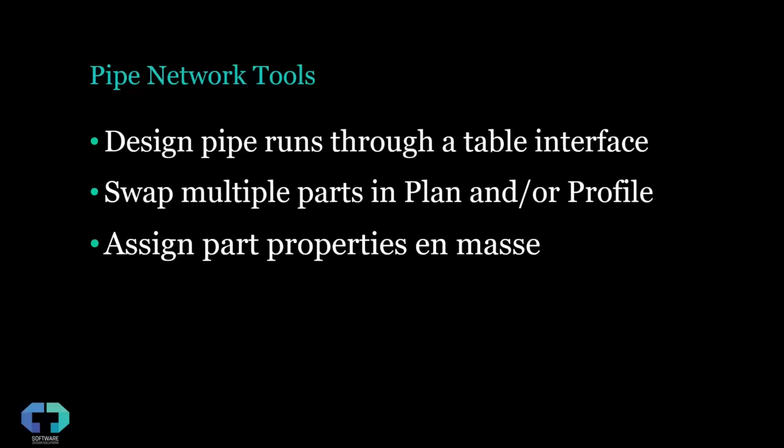Then we can also manage all the properties within our parts, in particular our structures, and assign properties in mass, like changing the reference alignment across all your structures at once, or perhaps assigning a casting to all your structures at once that meet that project requirement.